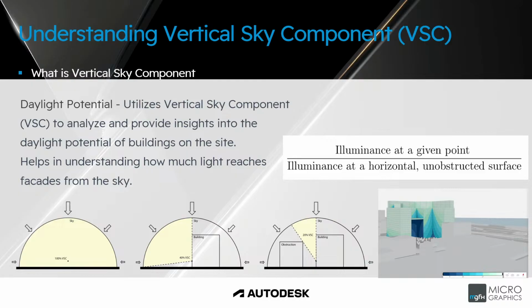vertical sky component. BRE, Building Research Establishment in the UK, explains VSC by the following definition: ratio of the part of illuminance at a point on a given vertical plane that is received directly from a CIE standard overcast sky to illuminance on a horizontal plane due to an unobstructed hemisphere of the sky. Generally put, it describes the following ratio.